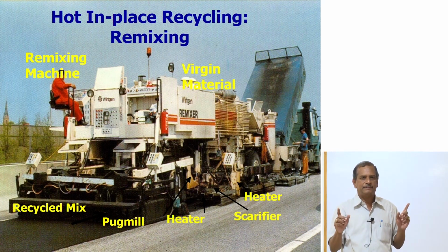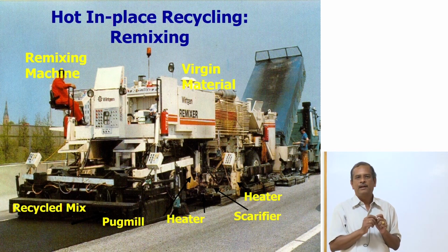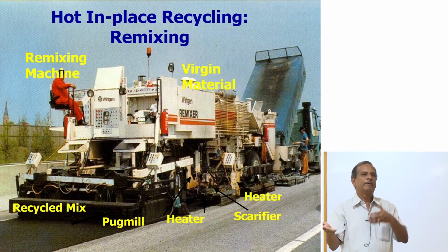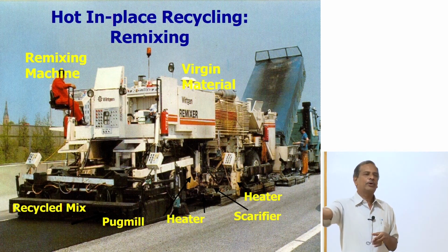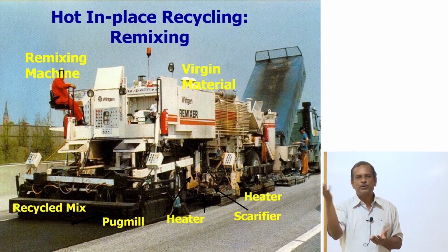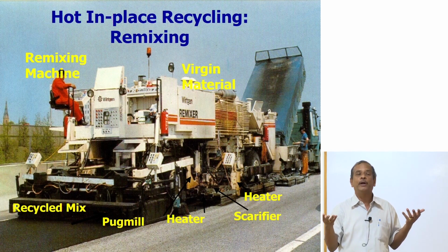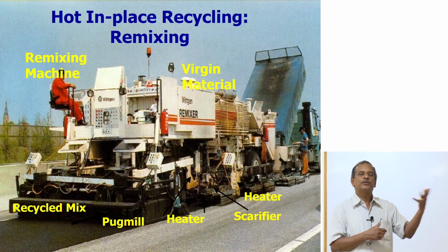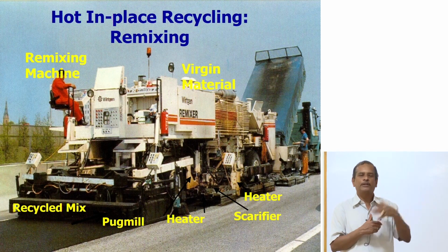Life cycle cost analysis, road asset management, pavement preservation, these are the techniques that you have to adopt when you graduate. So construction is one hand, and maintenance is the other hand. Maintenance challenges are like a doctor diagnosing a disease. You have a road that is deteriorated, for example, the campus roads. These roads were constructed in the year 2009. Now they are 10 years old. Now what should I do? As a civil engineer, you should be able to tell: should I recycle? Should I use a modified binder? Should I adopt white topping?